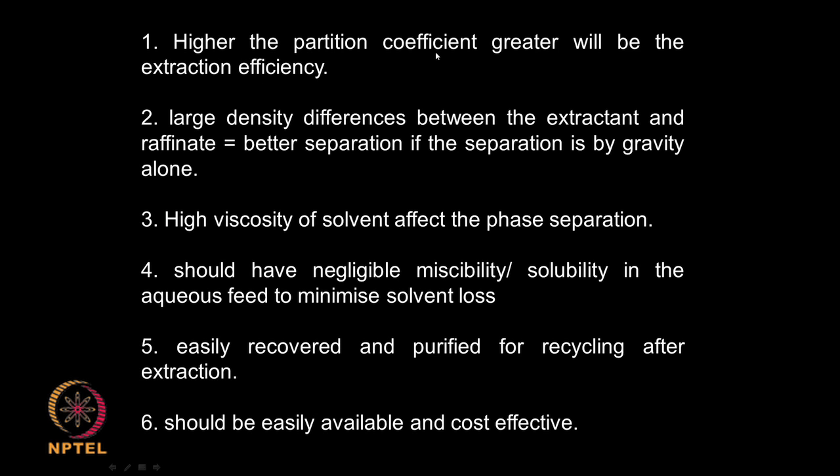So, higher the partition coefficient, greater will be the extraction efficiency. Okay. So, obviously, when I have a higher partition coefficient, greater will be extraction efficiency. I will not require too many stages for separation. Large density difference, better is the extract and raffinate separation, right. If the density difference is very high, the phase separation is very fast and very effective. If the density difference is very small, phase separation is not very efficient, then I need to wait for a very long time and I will not be able to really see the phase separation.